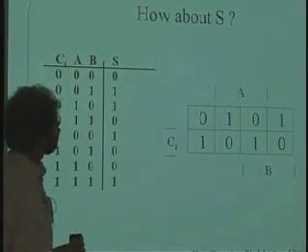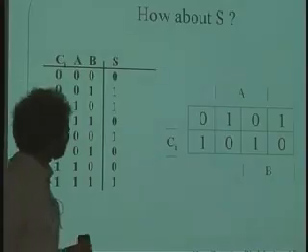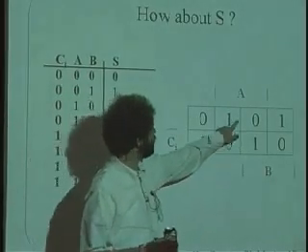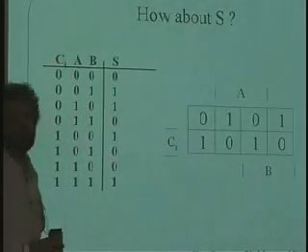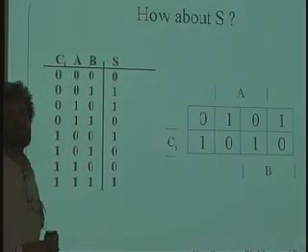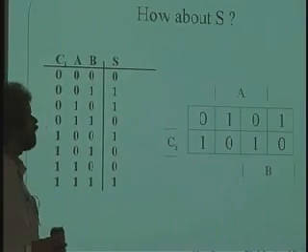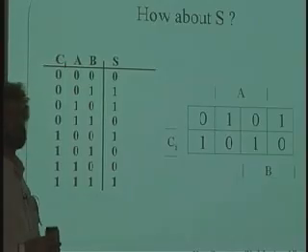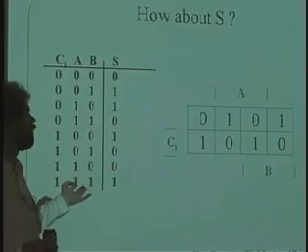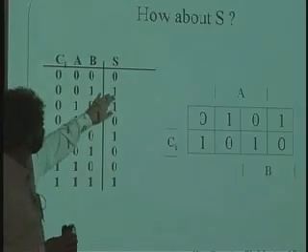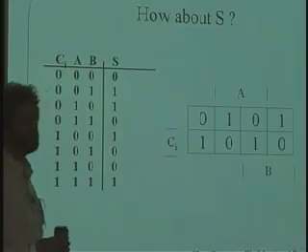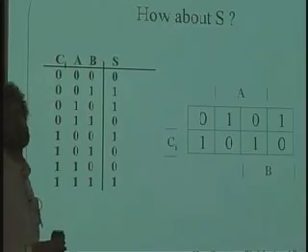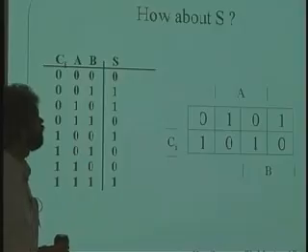And so in order to generate this, I have to basically put a circle around every single one of these ones, and then I have to ask myself the question, can I coalesce them into bigger terms? And the answer is no, I can't. So I can't make a sum of products form that's any more simple than having 4 terms, which we saw at the very start, which take into account the individual rows where S is 1. Because this is basically saying, is the number of ones in the input odd? That is what S is. And so it's exactly the parity function.